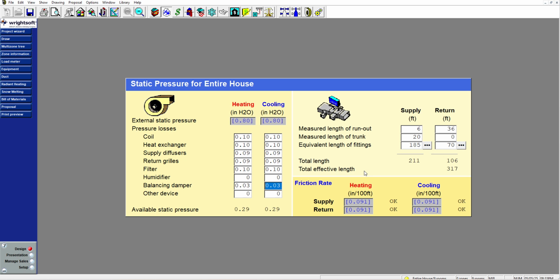things that contribute to pressure losses are accounted for in terms of their effective length. So let's say we have a 10-foot length of ducting, okay? Nothing blocking it, it's clear. Now the fact that the air has to move over the metal walls of the duct, or whatever material the duct is made out of, there is some amount of pressure loss. Over 10 feet, it's minimal. Over 100 feet, it's not minimal. It needs to be taken into account.